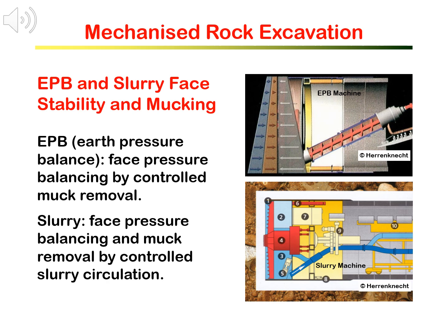The two common shield TBMs with face support are EPB, earth pressure balance machines, and slurry machines. One uses the excavated earth in the cut-head chamber to provide pressure to the face, and the other uses pressurized slurry in the chamber to apply a hydraulic pressure to the face.